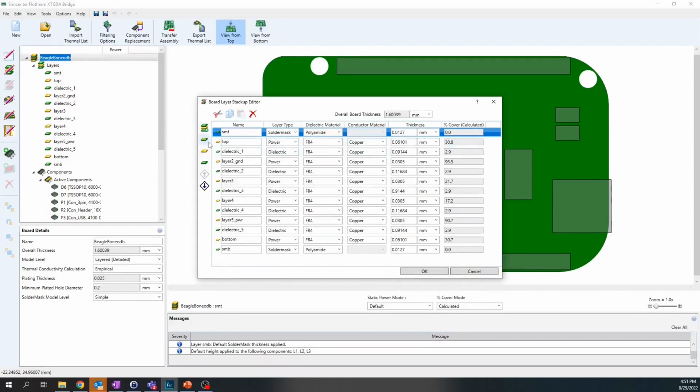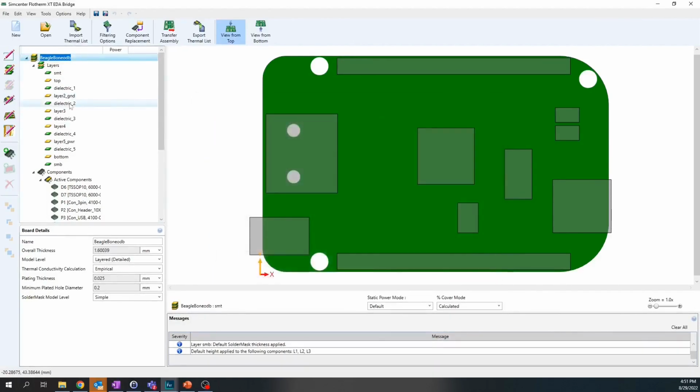So if you go on to add a new solder mask layer, it will not let you add another material. Despite that, if you change one of these layers to solder mask intentionally, the OK would get disabled. So that's how you bring in solder mask layers or add them in your board if it doesn't have two solder masks.